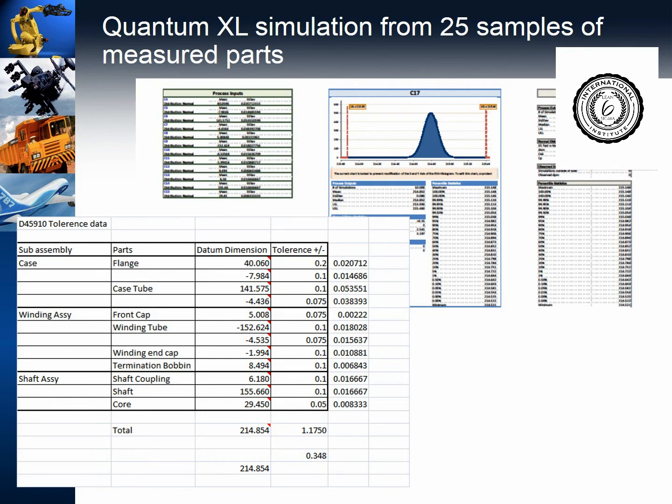Then one of the things we've done is taken a look at the tolerance stack up. So what does the design create? Should the design create that off-center distribution that we saw earlier? If we stack all the tolerances up, what actually should happen? Well, here is a Monte Carlo simulation. So this is a calculation. It's a prediction of how the tolerances should act and react.